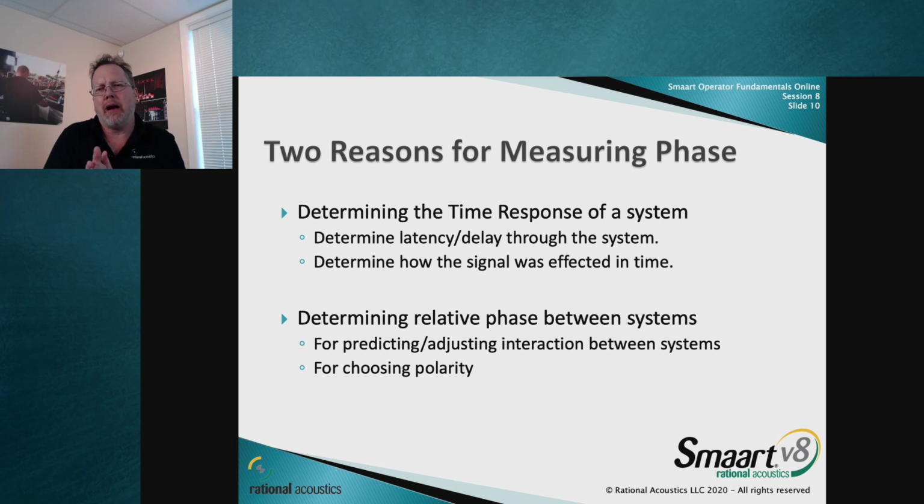What we're going to find out very quickly is that when I send my signal into the system, not all the signals get out at the same time. Basically, whenever we filter the signal, we're going to smear it in time. So we're going to dig into that a little bit. That's that whole minimum phase type of thing coming in. So the first question we're going to be asking is, what is the time response of the system?